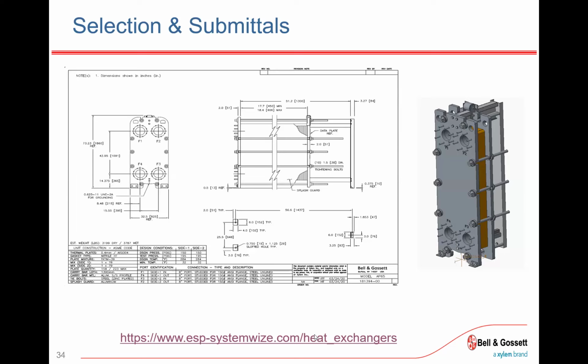You can make sure that we could say, for instance, under the performance requirements, you could start off with your excess surface area, or you could even put it under verify. Then next, you could have it under your extra plate capacity. So you say, I want to be able to add 20% more plates later, 30 more, so that when you do run the selection, you'll notice that it narrowed down. When you do get your selection, you don't then have to say, okay, what does this have for, oh, this only has 2% extra surface area. What do we have for plates? What's the potential plates? Just makes it easier.